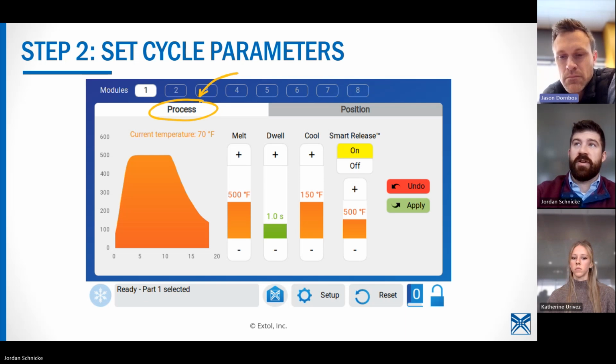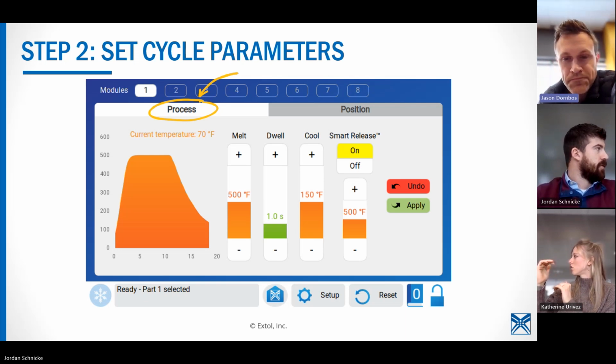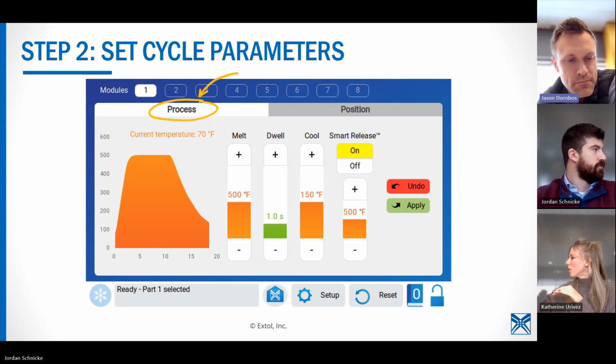Once it hits that, you're going to see this guy continue to go back down. Cooling air is going to start right away, and it's going to try to bring it back down to that baseline. The goal of it is with those materials that don't like touching hot things, after they're cooled down, it creates a little skin in between the boss and the heated punch so that the module can retract. Creates a little bit of a melted material barrier. Is that how you would describe it?